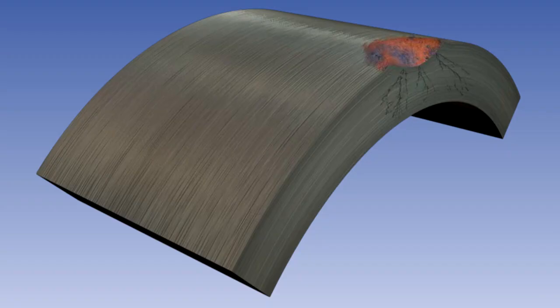A combination of a steady tensile load and corrosive environmental conditions produce a form of metal fatigue known as stress corrosion cracking. The stresses may be built in during manufacture, introduced during assembly, or may be applied during operation. Metal under stress corrodes more rapidly than unstressed metal. It usually begins with pitting at the surface. This increases the stress at the pit, causing a crack which can extend under the combined action of corrosion and load until failure occurs.